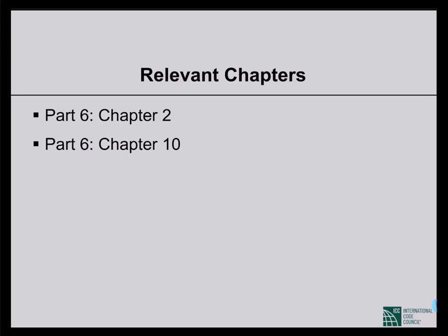Only chapter 2 of part 6, which deals with loading, we have to refer to in order to calculate load, and chapter 5 of part 5, which is materials. There are mentions of standards related to steel. But basically, chapter 10 is a self-contained chapter, and this is the longest chapter in the entire Bangladesh National Building Code. This one is the longest. So you can understand that